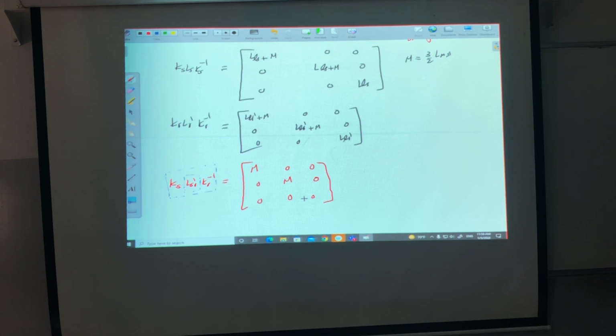Doctor, what is the value of M? 3/2 LMS. LMS or LMR? No, LMS. Always, I think when we refer, we convert all the magnetizing inductance in terms of what? LMS. Always all of them LMS. Yeah. After referring the rotor circuit to the stator circuit, we exchange LMR with LMS, the equivalent LMS according to the theory. Good.